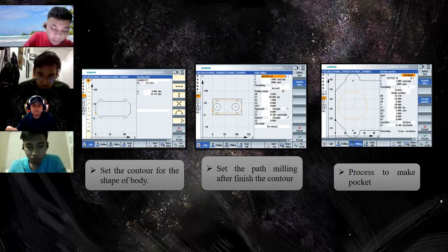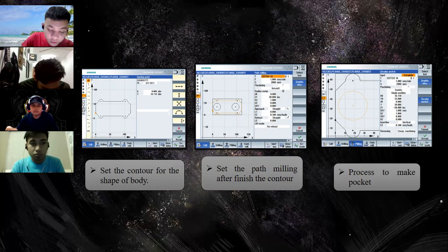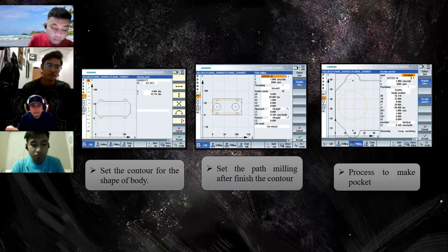We must set the position of the hole to drill. To make the position, click the milling and pick the position. After that, choose the position style that you want to use. After that, set the distance for X0, Y0, L1 and L2. After setting the distance, you must set how many drills you want in N1 and N2. After settling the drill process, we can make the simulation.